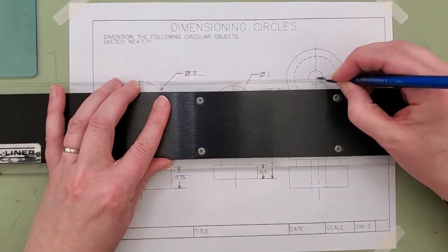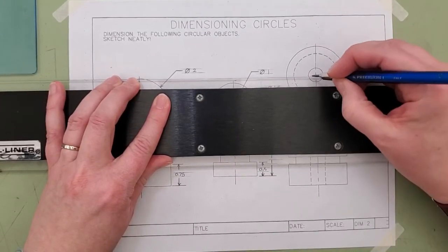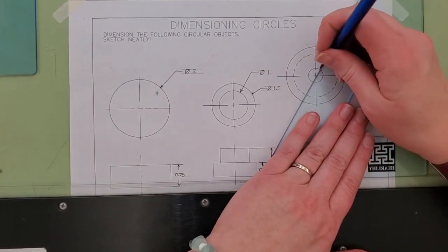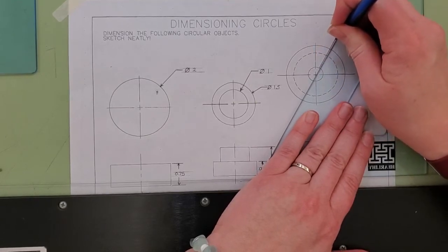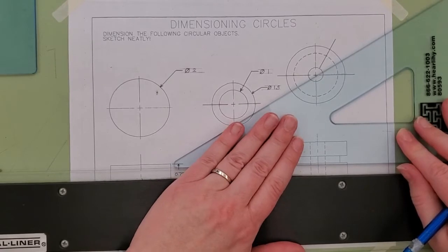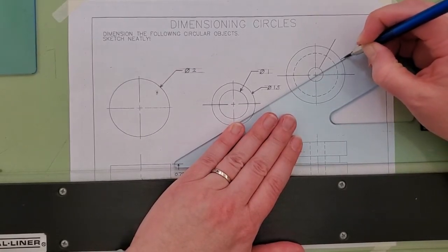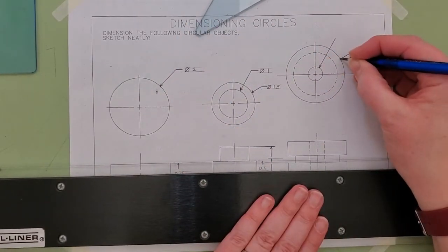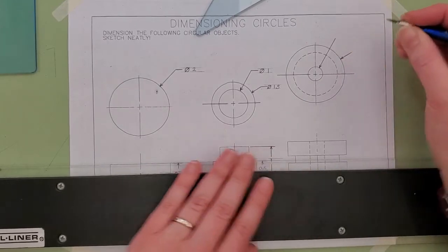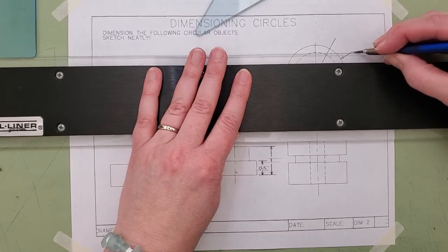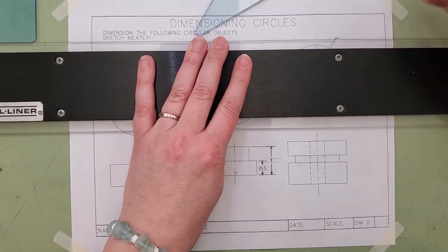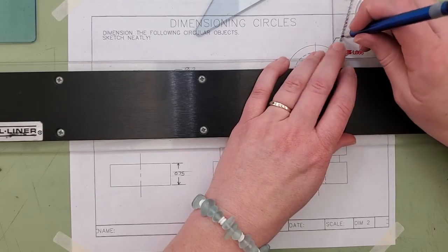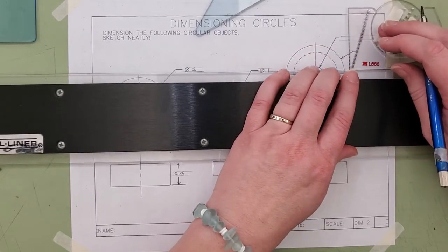Okay, so I'm going to get... I don't know why my center lines didn't photocopy well, but yikes. There we go. So I'm going to create my extension lines, my leader lines for my circles. Okay, make sure I have my arrows. That's one of the biggest things people forget, the arrows on their leader lines. Flatten out to horizontal. And the numbers go beside it, not on top of it, not underneath it. The numbers go right beside that horizontal bit of your leader line.